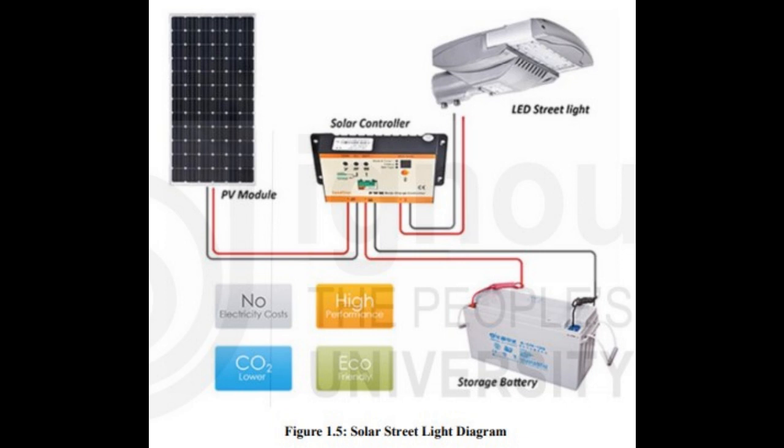Look at the screen. How do these solar street lights work? The solar panel, under the control of the intelligent controller, captures solar energy and converts it into electricity when the sun's rays hit the solar cells. The storage battery is charged by the solar battery during the day, and then it powers the LED lamp at night. The controller plays a very important role in protecting the storage battery from overcharging or over-discharging.